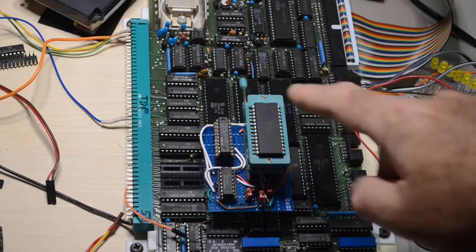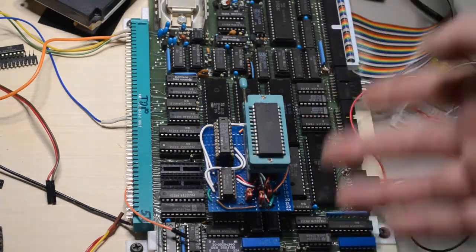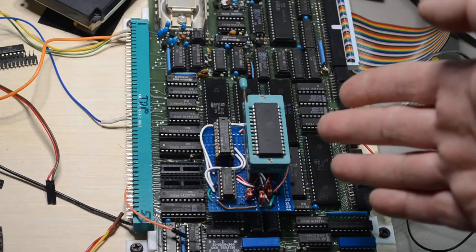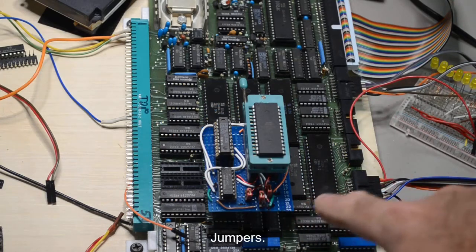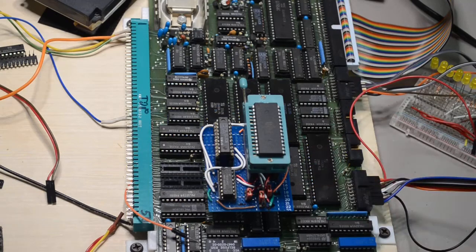So I've got a much bigger ROM here. I needed at least 16K of space to get my monitor and Grant Searle's implementation of Microsoft BASIC in here. So I've got a 28C256 EEPROM here. I'm only using the lower bank of it. I can actually have switches here on the daughter board to switch it to use either the upper or lower 16K bank. Right now we're just using the lower 16K bank, and it works.